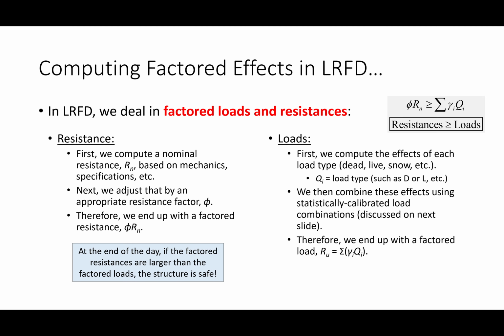Okay, so the way that it works is on the resistance side, resistance is all about strength. How much a connection or a member can hold up before it's going to fail. So for example, if we're talking about shear in bolts, so you have a bolt, how much load does it take to shear the bolt in half? So we calculate the capacity of each bolt in shear, how much it's going to take to snap that in half. Multiply that by the number of bolts that's in the connection, and boom, that's the capacity.